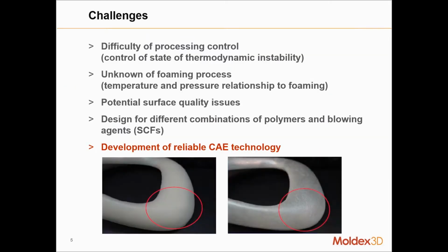When you talk about the challenges involved with foaming, there are multiple different challenges. As can be expected, depending on the stability of the foam itself, there can be a challenge in controlling the process to get the right part quality: trying to understand your temperature and pressure relationships, gas dosage amounts, or anything of that sort. Like I said, we are going to touch upon each of these topics briefly.